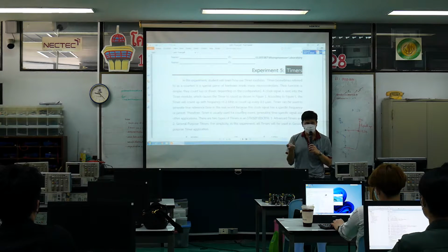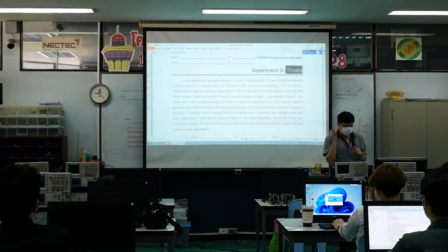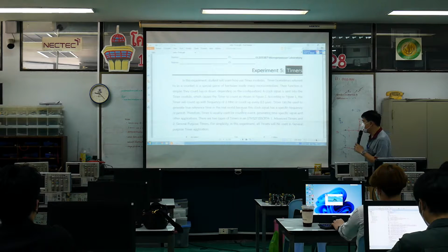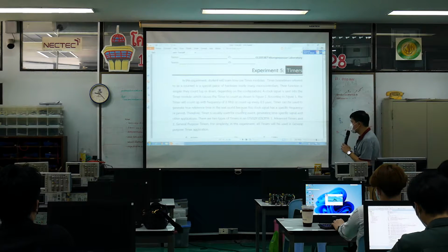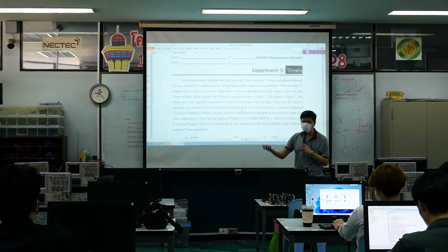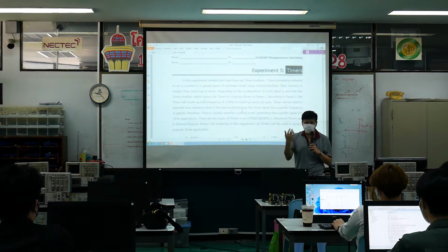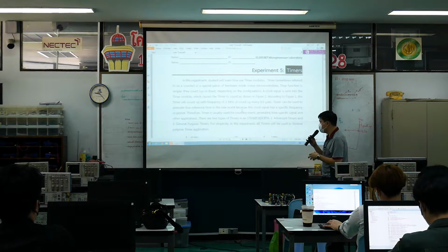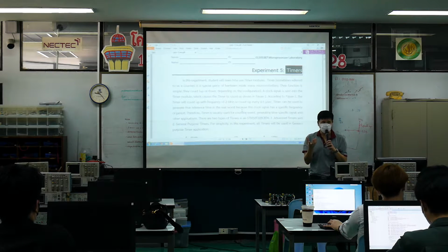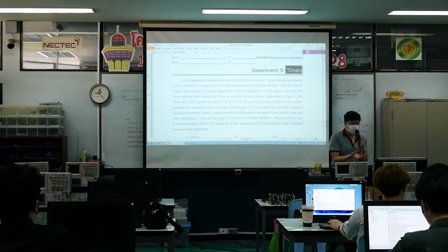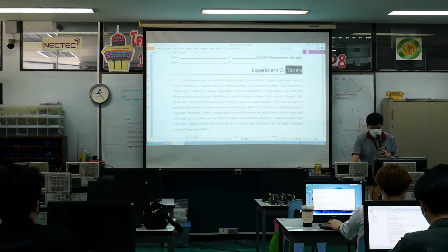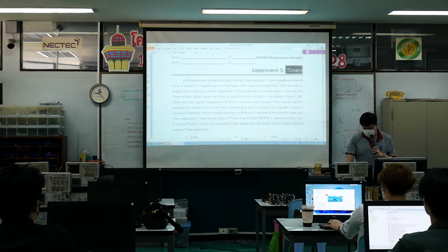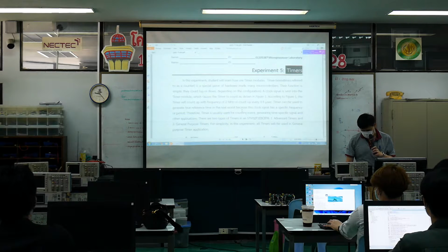And you use an oscilloscope to capture and see that delay in real time. The other thing is that the timer is like a clock, so it's counting up or counting down, right? And the counting depends on the frequency of your CPU. Therefore, in this case, we will use the counting property of our timer as counters, and to use other devices that are useful for our electrical engineering.